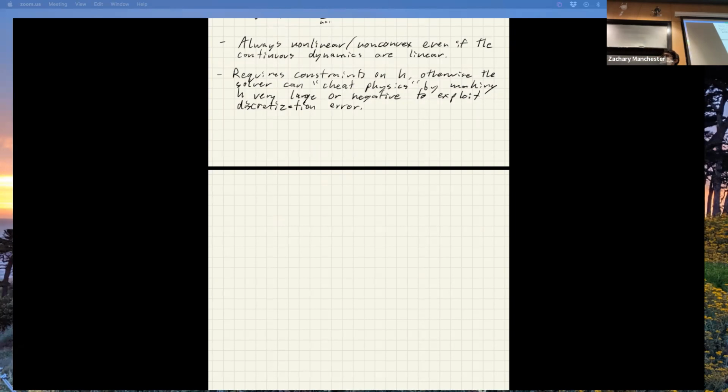So you mean basically letting each time step have its own H versus having one global H? Yeah. If you do one global H, with the kind of stuff we talked about last time, where you tack on this additional fake U at the beginning, you get this kind of ill conditioning, vanishing, exploding gradient, tail wagging the dog kind of effect, because it's affecting the entire trajectory. And it's this one parameter all the way at the beginning. So you have to backprop the gradients and Hessians of that stuff all the way along the trajectory.